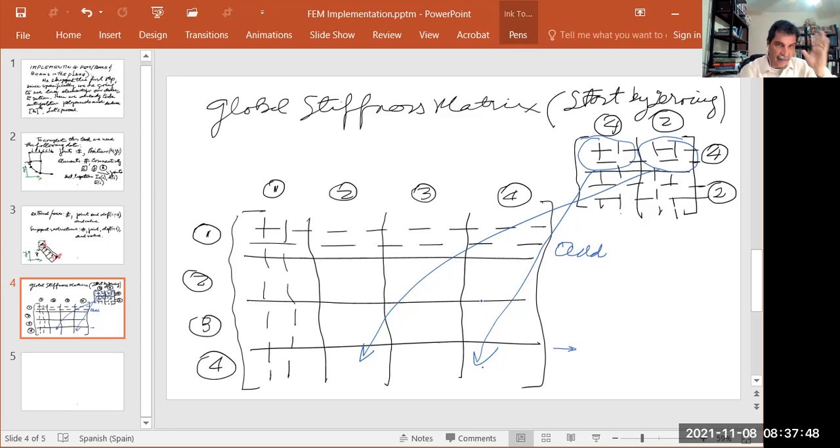The column number is the same thing: the number of the joint minus 1 times 3 plus 1. And then you have this value here. For the other joint, you will identify this point here, just knowing the number of the joint. Question, people, questions?